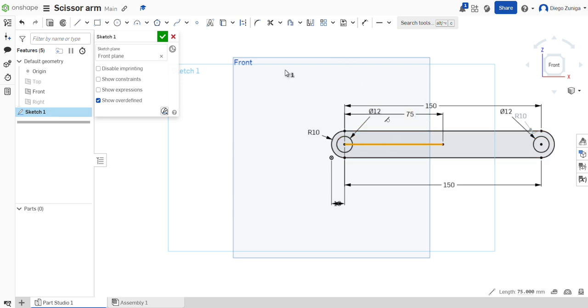So in order to create a line that's going to be used as a reference, we're going to turn it into a construction line. So this tool is going to be applied to this line. Notice how the construction line is a dotted line, which again is not going to appear in our model. And having done this, now we're able to make a third circle, whose origin is this. Its dimension is also going to be 12, just like the other ones. Cool, so now I can select OK. Everything is well defined.